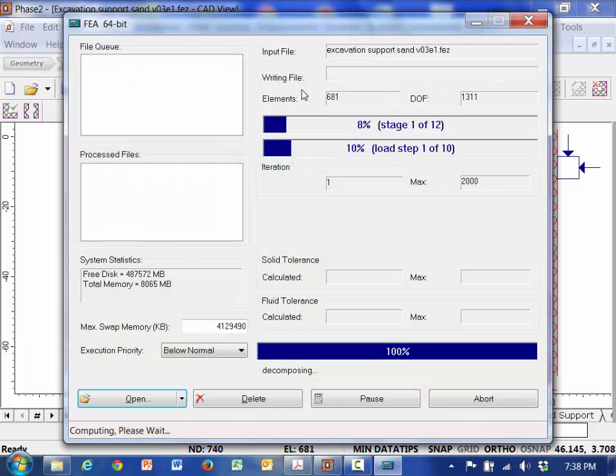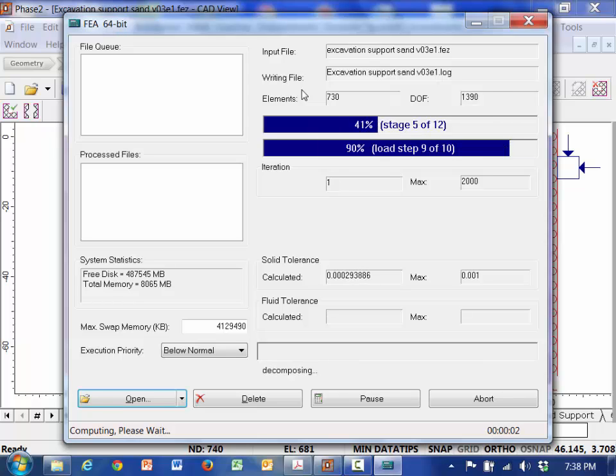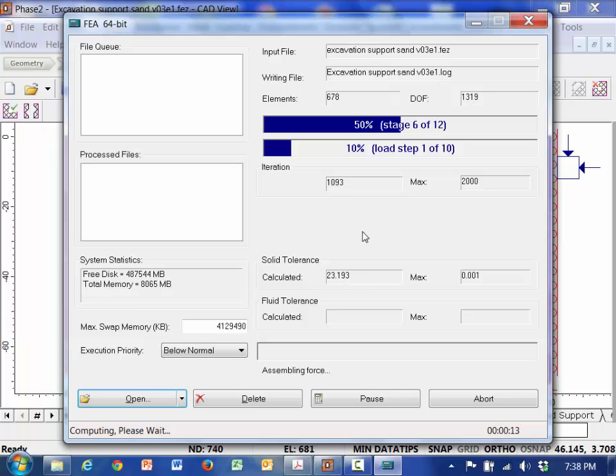It's really important that you watch the computations and make sure that it's converging, because it's not going to tell you. So right now it's having a hard time converging on this particular phase. In fact, you can see that it's not going to converge. If you just happily run along and let this thing calculate, I got this to converge the other day, so I don't know what's going on. It'll finish the program, it'll plot stuff up, but the numbers don't mean anything because the problem hasn't converged.